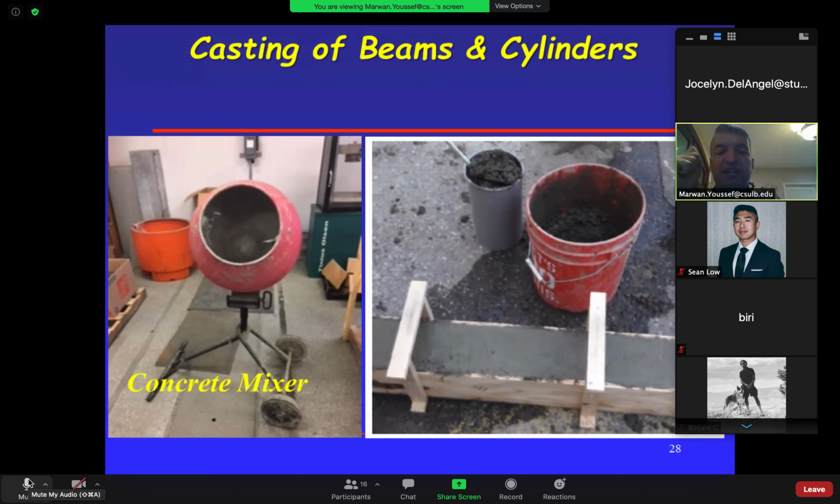Since you asked, we can go into some depth here. It's okay to spray some water if it's a hot day and some evaporation took place. But by code, the concrete truck cannot come too early to the job site. They cannot stay, I believe, more than 1 hour waiting for you to get ready.